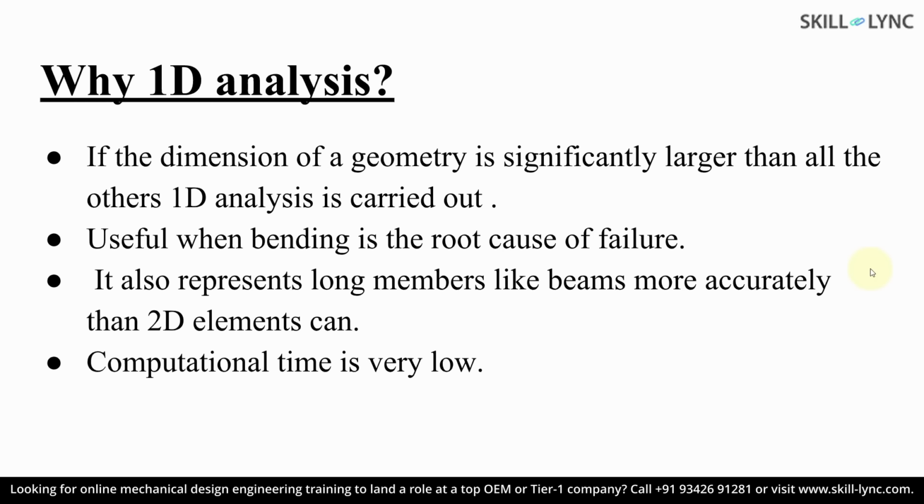So if the model that you are going to use in your FEA analysis has a dimension which is significantly larger than the other dimensions, then we tend to go for a 1D analysis to obtain the required results. For example, let's consider a long beam, and I am interested in looking at the deformations caused by bending. Since the beam is long enough, a 1D analysis is sufficient to produce the required results.